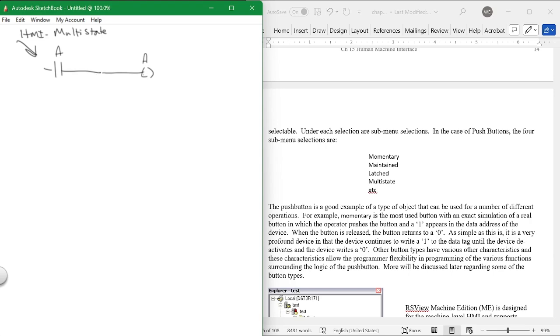And it changes this bit right here, which also changes this bit right here, by the way. They both change at the same time. So this acts as a seal circuit. But note what you can do. You can put in things that can stop it if you want to. And you can also put in things that can be done in parallel with it, like this.